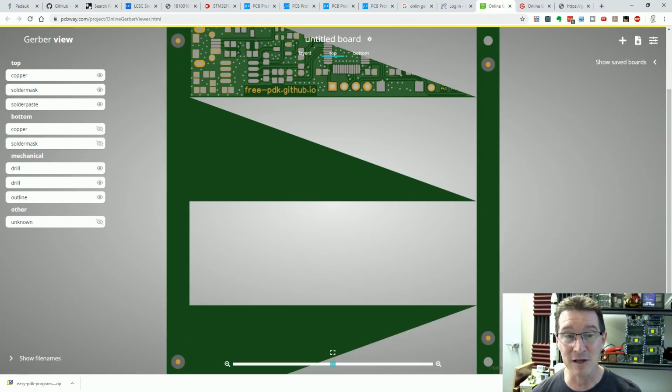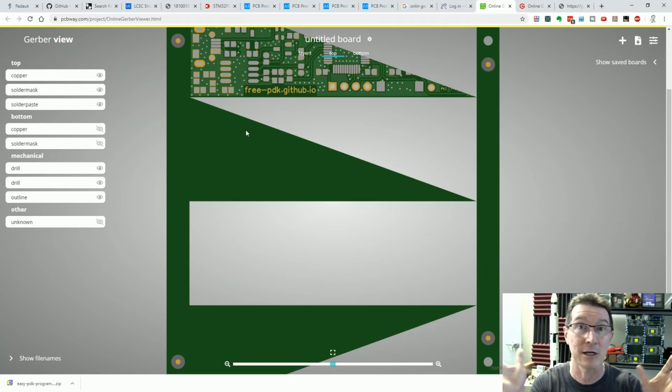And as I said, even if this was imported properly and did actually copy over, you would still have the issue of them questioning, oh, this looks like a panel, because they're experts at doing this. They do it 100 times a day. And they'll go, oh, this looks like a panel. You want us to make a panel. Do you want V-scoring, or do you want routing in here? And I believe this one didn't have enough room for the routing in there. So it's got to be V-scored and things like that. And then they won't do that on the prototype panel, as I said. And it's just a whole end of problems. So just don't do it. Just don't muck around with panels.